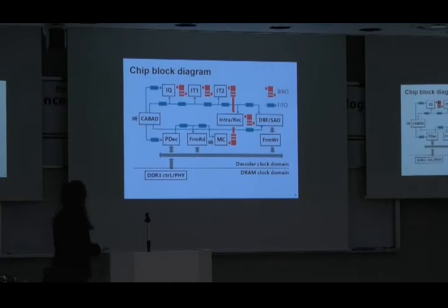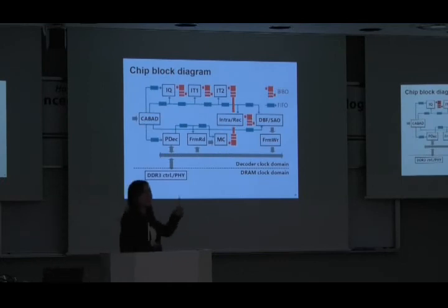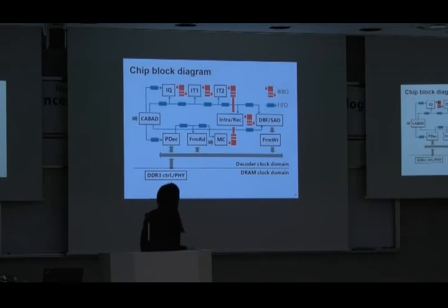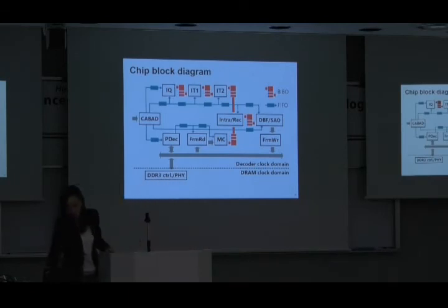Now we have two ideas: one is BIBO, another one is relay FIFO. BIBO is here, the orange one, used to store the pixels, and the relay network FIFO is used to store the parameters. This is the final whole architecture. We delete all of the triple buffers by using the BIBO and the FIFO.